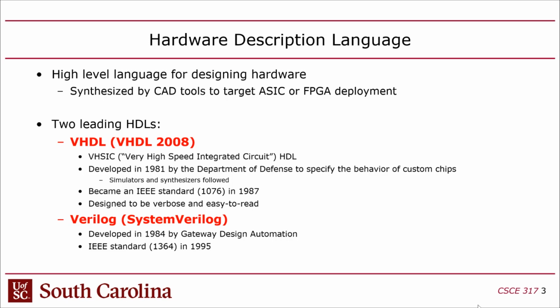Chisel is a language that's actually an upstream language from Verilog. So when you write code in Chisel and you run it through their compiler, they still generate Verilog, right? So basically, Chisel is kind of a more abstract language. It doesn't replace Verilog. You're still using Verilog if you use Chisel, but Chisel is acting almost like a script that you're writing to generate Verilog.